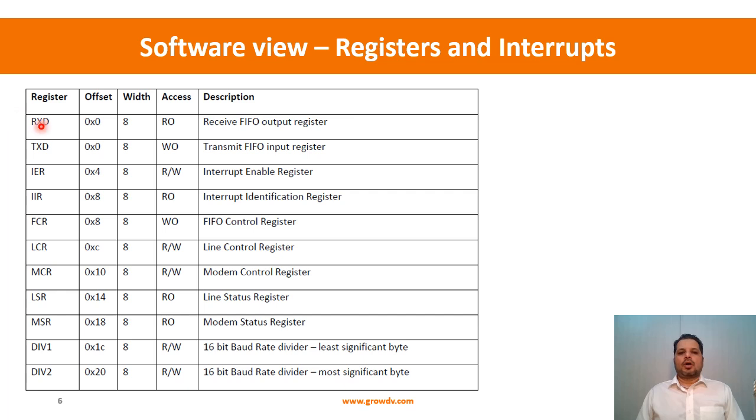Now on the bus, when the access comes to this particular peripheral, the peripheral will typically always see the offset, or the address coming in on the APB bus, to be hex 00 only.